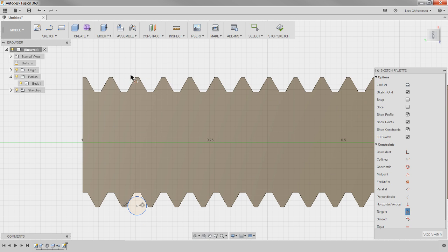And I've seen people just not putting 2 other wires in it, just do it flat in here. I really don't recommend doing that, because as soon as you do that, now you're relying on the diameter of this part. And what we're really trying to measure is the thread, right? Like if you're thinking about any screw that you're screwing into something, at least in machining, the diameter never touches anything. It's all about the location in here.